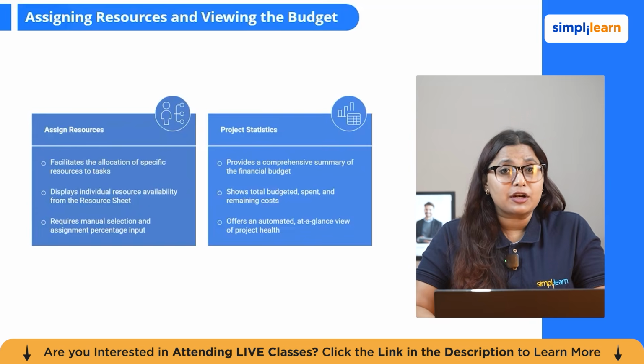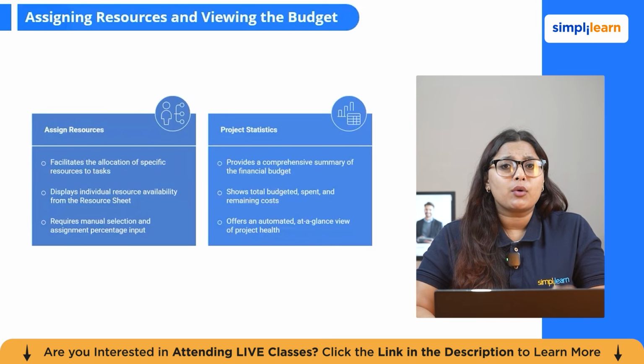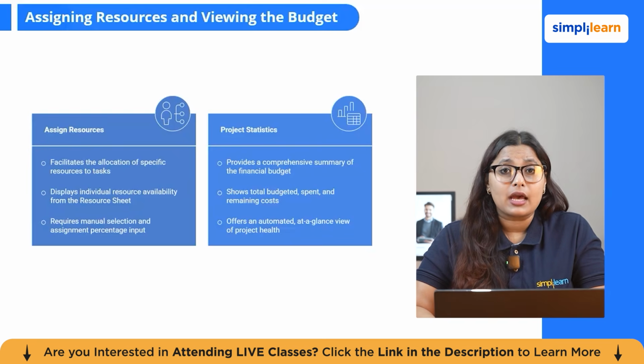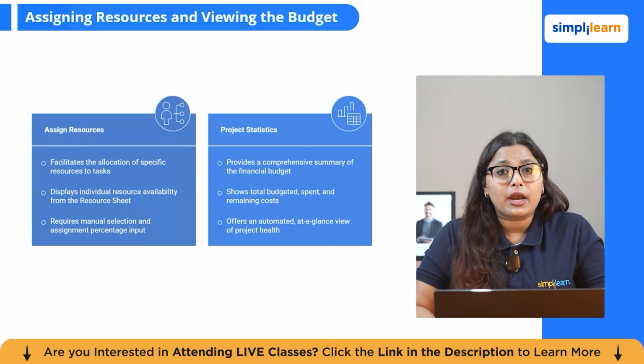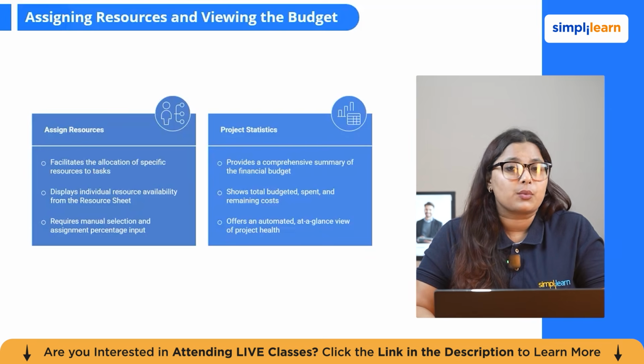You can assign multiple resources to a single task. A foundation activity might have a site engineer at 100%, 2 machines at 200% combined, a quantity of concrete in cubic meters, and a crane at 100%. Each one contributes to the task's total cost. MS Project shows you all of this broken down by resource in the Task Usage view, which is an extremely useful view for detailed cost review and for conversations with your quantity surveyors.